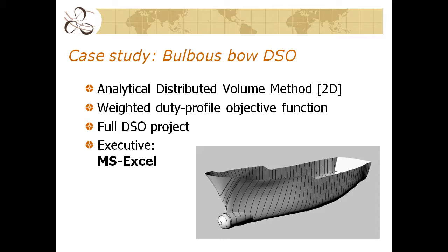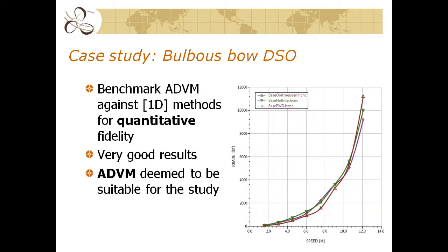in Excel. And Excel then mathematically modified those for the different hull or bulb parameters: the cylinder volumes and wetted surface, the hemisphere volumes and wetted surface, changes in longitudinal center of buoyancy, etc. And this longitudinal distribution we could then use within that ADVM method, the 2D method inside of NavCad.